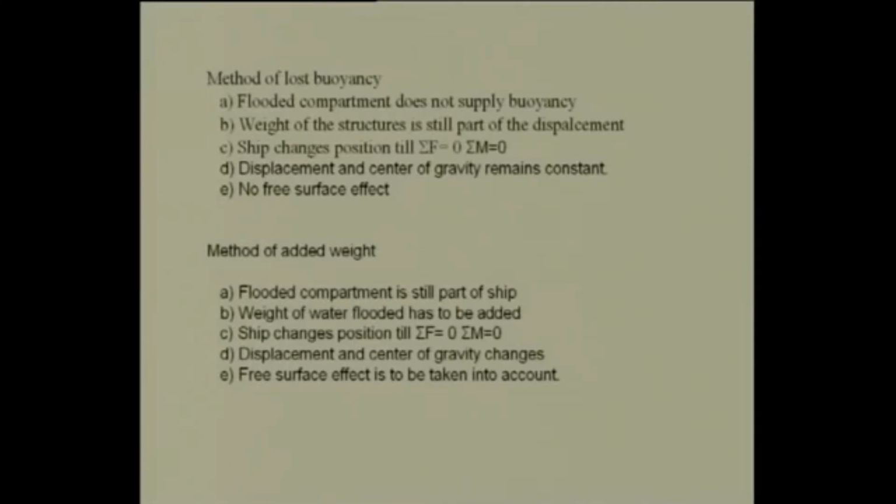So, what it says is that the flooded compartment does not supply buoyancy. Now, you can see that the weight of the structures is still part of the displacement of the ship. Okay. Then, since the weight of the ship or the position of anything in the ship has not changed, the displacement remains the same, the displacement of the ship is the same, and the center of gravity has not changed, because none of the items in the ship are being changed.